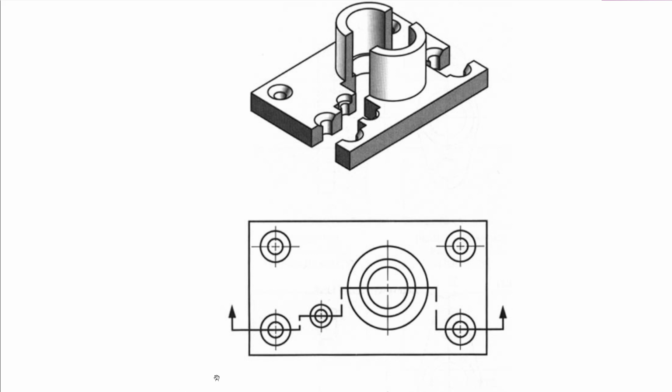So when you are sectioning this one, you may want to ensure that you are able to get through and reveal all the features of this object. And those which are identical, you may not have to reveal all of them. You just need to reveal only one, so that it gives you information of how those features will look, even at the other ones.